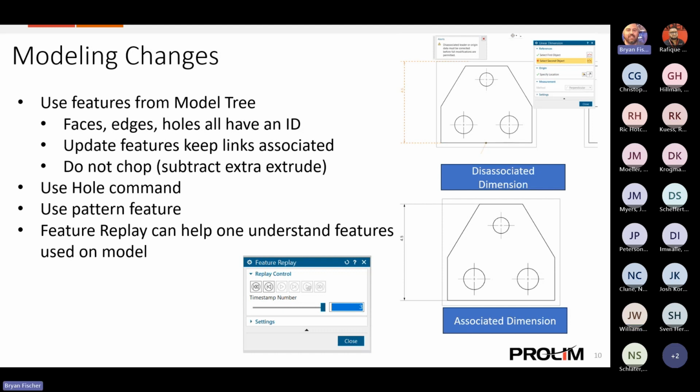I have seen it where the model was pretty dirty, and let's say it was something that could be done with three commands and somebody had like 10 commands for no reason. I've seen it where we've said, hey, just go ahead and remove that and then either remodel it or, like you said, remove the parameters and use synchronous for that.